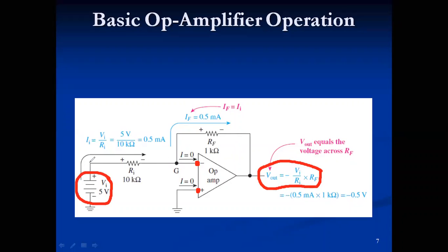All right. So what is the purpose of this circuit? It's going to take the 5 volts. It's creating a current that's based on the resistance here. I know what the current is. You know how I know what the current is? Because I know what this voltage is. Remember I said that is the ground voltage because this is grounded, and this OpAmp is forcing these 2 voltages to stay the same.